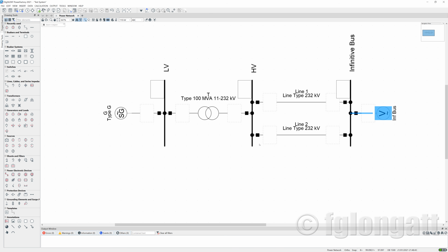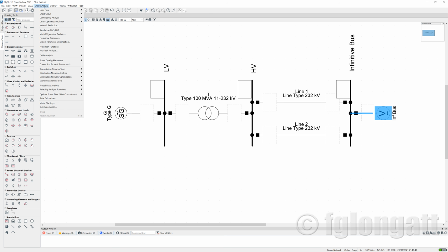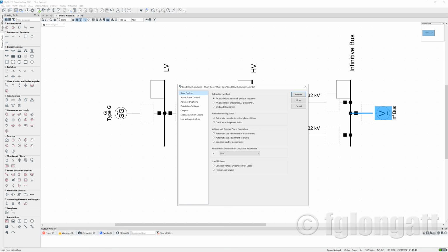And to run a load flow, there are many ways to do it. You can go here to the top, to the tool bus bar, and you can find here load flow, and you can say load flow, okay? That is one option. I call that the elegant way. People that know how to move between menus inside the DIgSILENT PowerFactory. That indicates some education and some skills using the software.